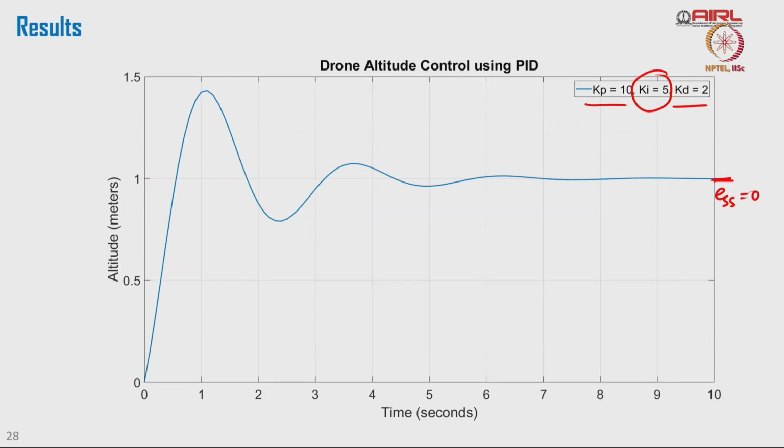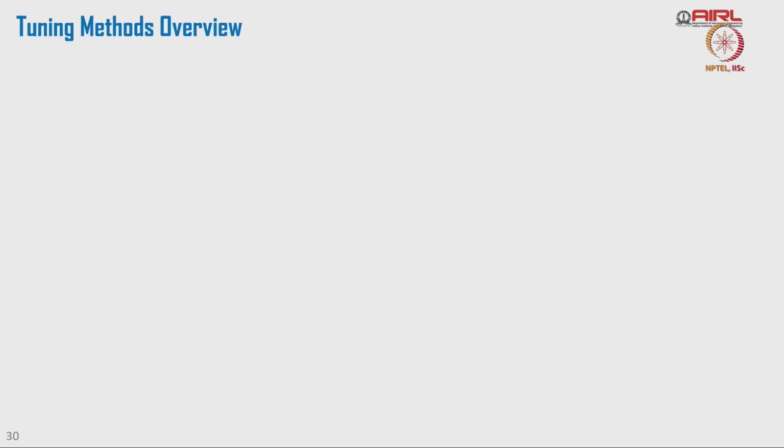Then we increase Ki, but we are not properly tuning the controller, because see, when we make Kd from 0 to 2, we do not know whether 2 is sufficient or not. When we make Ki increase it from 0.5 to 5, we do not know whether 5 is enough or little lower value is also fine. So, tuning is required. Okay. So, manual trial and error is one process which can fix the problem, but it might not be always very intuitive and can be tedious.